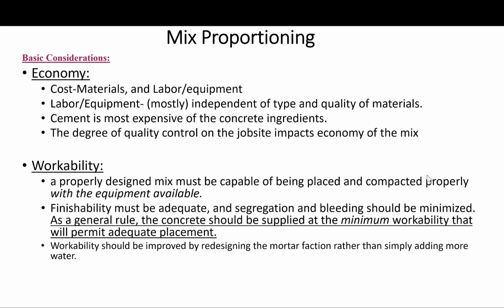Where necessary, workability should be improved by redesigning the mix to increase the mortar content rather than by simply adding water or more fine materials. Remember, it's easy to add water, but it cannot be undone.